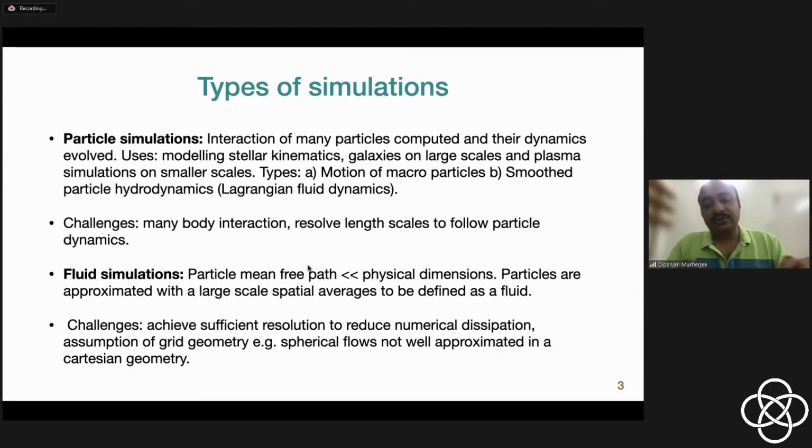For example, if you have a Cartesian coordinate system, and if you are modeling a spherical flow in a Cartesian geometry, then you invariably lead to an instability called the carbuncle instability, where the edges of the grid start showing funny behaviors due to the poor discretization of the space. The way to resolve this is just increasing the resolution, so your small cubes well approximate the